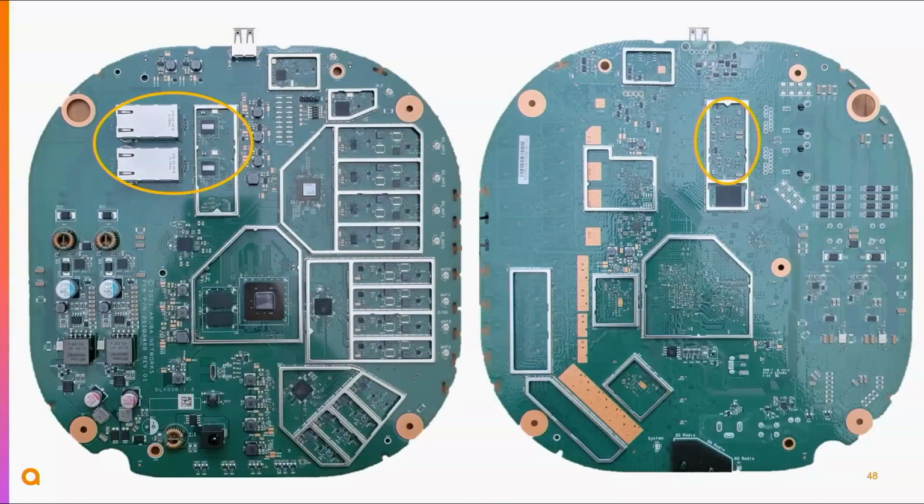So that sits here. Those are those connectors. On these APs, we have side entry for the Ethernet ports. In the past, we used to go this way. That's another subject for discussion with some people. There are different schools of thought on what's the best. It goes in here, the PHY components are here, and there are lots of other components involved, but eventually it goes into the system on a chip here.